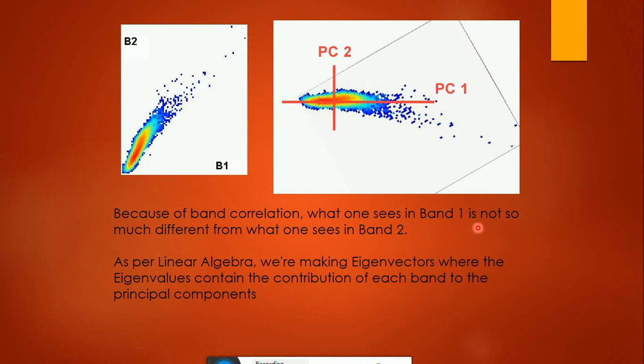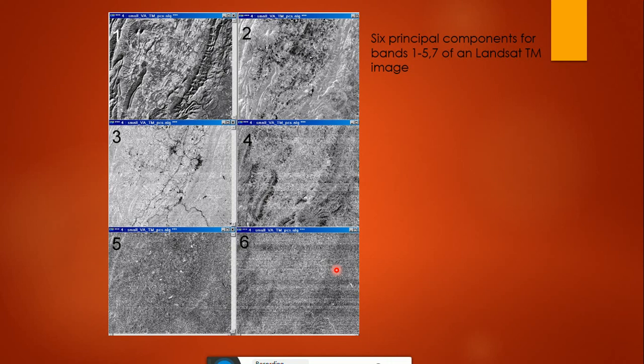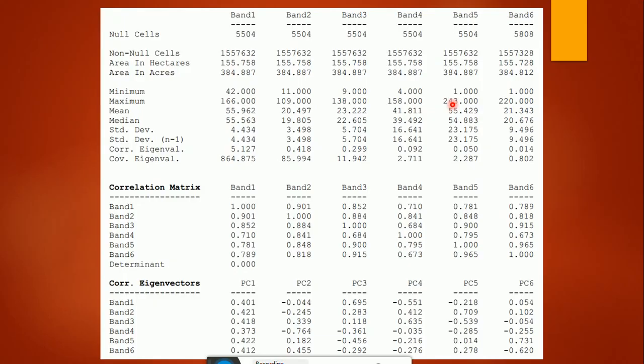Image classification is the science of turning remote sensing data into meaningful categories representing surface conditions or classes, also called feature extraction. Spectral pattern recognition procedure classifies a pixel based on its pattern of radiance measurements in each band, more common and easy to use. Spatial pattern recognition classifies a pixel based on its relationship to surrounding pixels, more complex and difficult to implement.